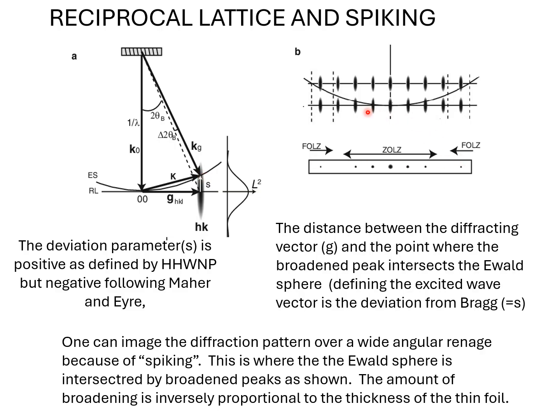And that means we're sampling numerous points in diffraction space. We actually see a range of angles, we can call it angular space, wave space, reciprocal space, whatever you want, but it corresponds to diffraction angles, and we see a range of angles instantly all at one point, especially if we're on a zone axis.